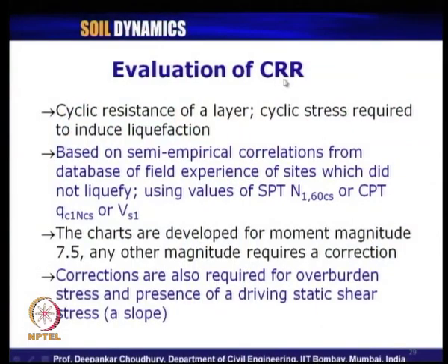Coming to the other component, that is evaluation of CRR, the cyclic resistance ratio. So, how much capacity the soil has to resist liquefaction until it liquefies or fails. Cyclic resistance of a layer is nothing but the cyclic stress which is required to induce liquefaction.